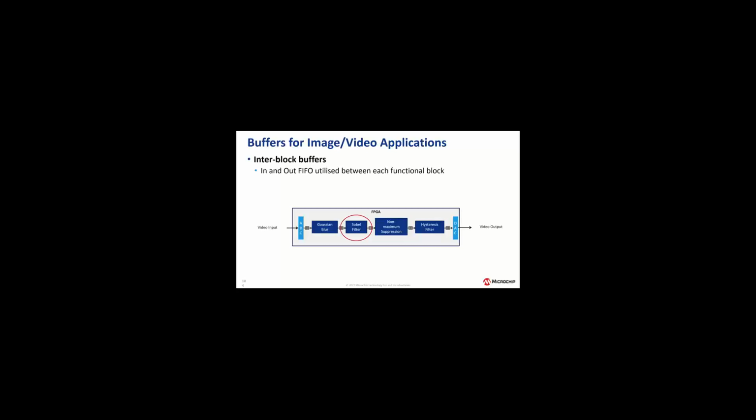Between the blocks, however, I've got to get the data between the two because now I'm streaming through. I'm going to run data through. So I'm going to put FIFOs in between effectively each of these blocks so they can pass data between them. And I need to put that into my code as well. So effectively, this time it's going to need a few more modifications to make use of some underlying libraries. Okay, so the libraries effectively, look at them as hardware modules that we've pre-written to make better use of the architecture.